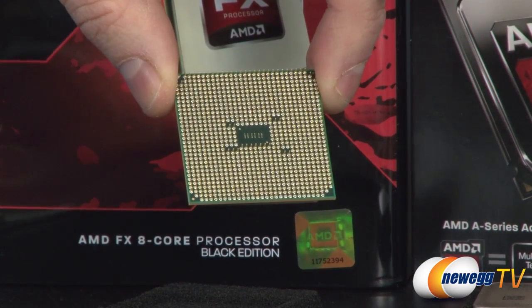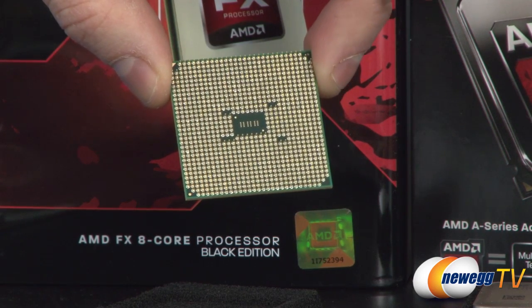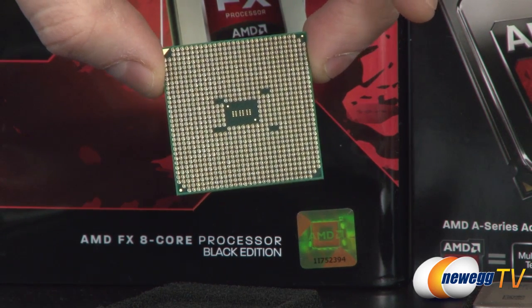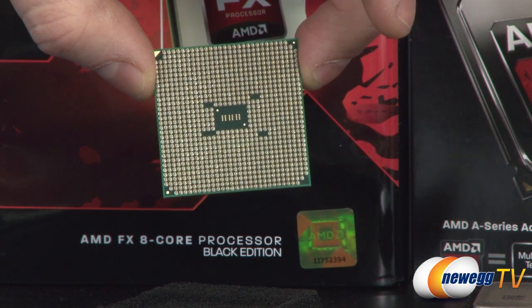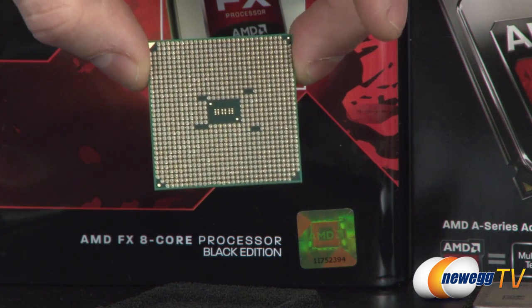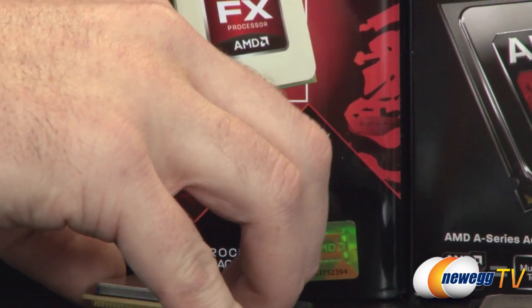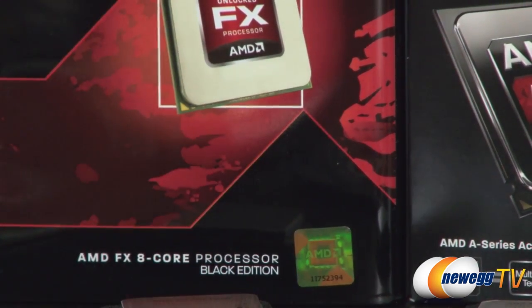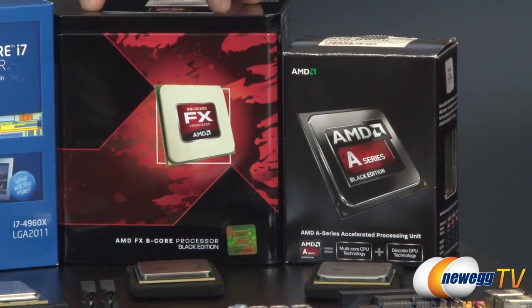They're very delicate, so this is one of those elements when you're installing a CPU into a motherboard where you want to be really careful of the pins. In fact, my finger actually touching some of those on the edge is not good, but I'm being careful, I promise. So the FX series of processors from AMD go more towards their performance processors. You can get them in up to 8 core varieties, which is really good if you know that you're using software, for example, that's heavily multi-threaded and can take advantage of all those cores.